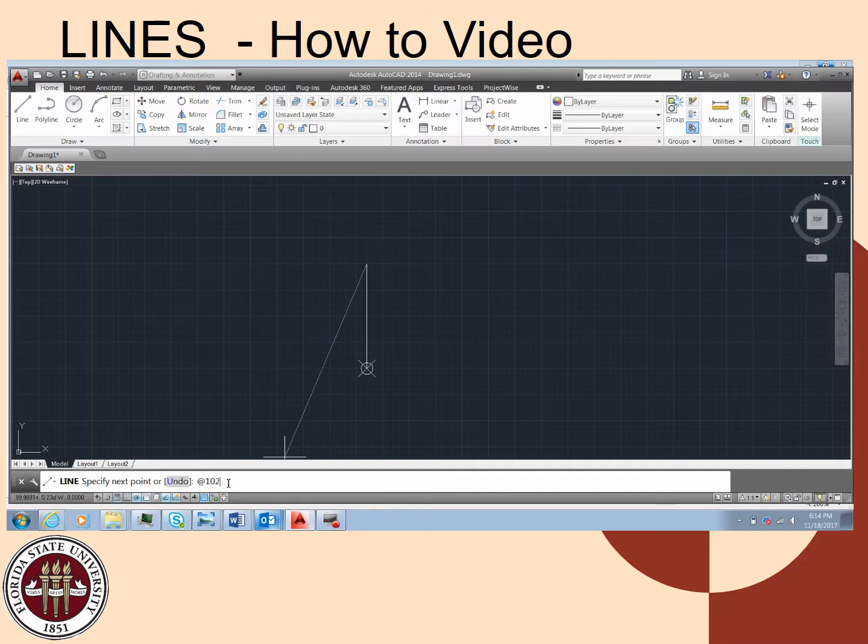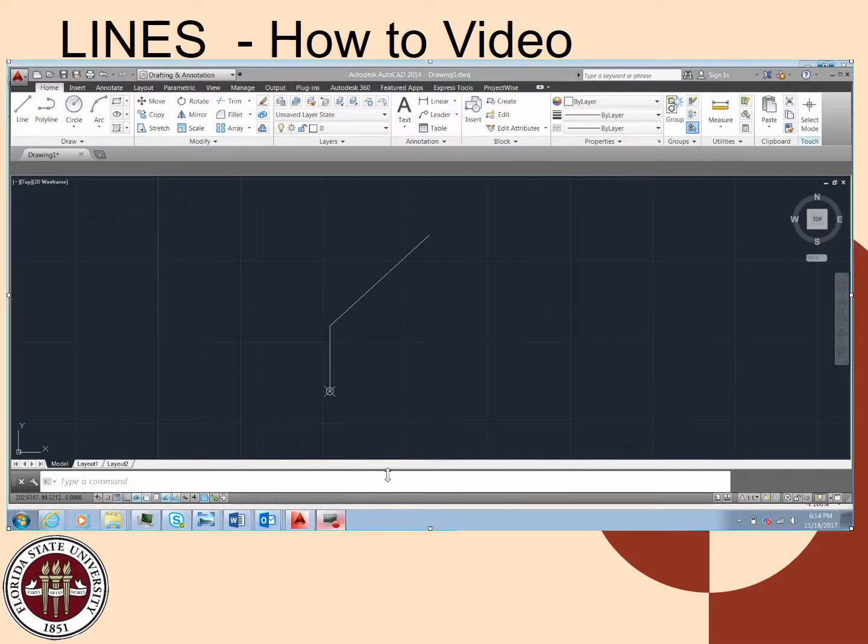All right, our next length can be 102.745, which is typical of a survey, at an angle of north, 47 point, I don't know, let's make it 238. And we have to select either east or west, and we'll select the east. So it has given us the correct line using the azimuth and the length that we selected.